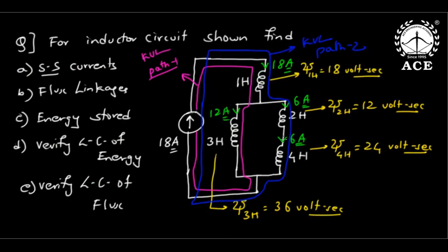In parallel inductors, what is the same? Voltage is the same? No, you cannot say voltage here because it is DC steady state now, voltage is 0. So in parallel inductors, what is the same? Flux linkages are equal. Currents will divide. So that means you cannot take 2 times. That is a concept. That means fluxes also will divide. Like charge divides in a capacitor and current divides in a resistor, fluxes also divide in an inductor.